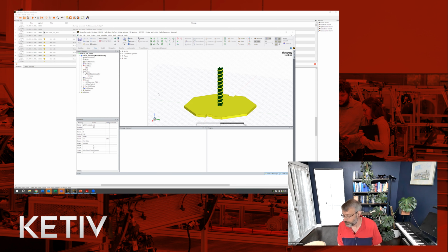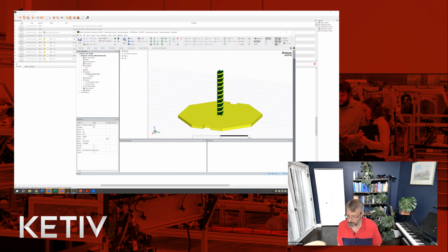And as you're setting up your analysis in terms of your solver, maybe you want to use the planar solver instead of the FEM solver, which can be faster. There are a number of tips and tricks that I've done in other videos to simplify your analysis and simplify the geometry that's here and how it's been done, so that we get the time for an analysis to be as small as possible.